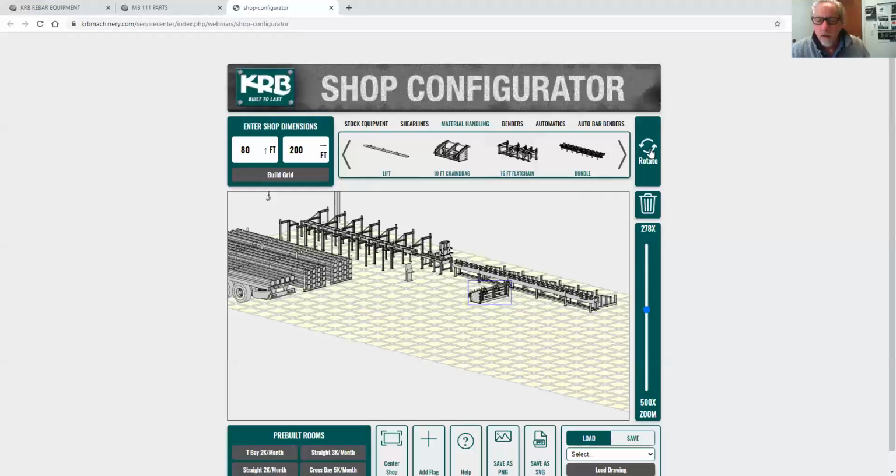between them. And the way that these fit in is they butt right up against the conveyor. So the measuring table would discharge onto these, and then they would convey on to the double bender. And I'll show you that here in a second. So I'm just going to go ahead and drop 3 modules in here real quick. Place them in here, and then I want to add a double bender. So this system will, without a crane pick, automatically convey bars to a double bender.